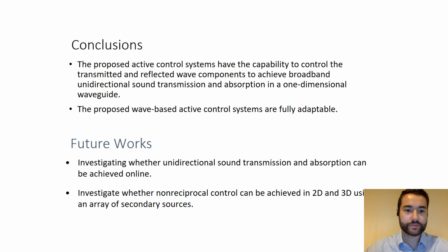So the conclusions of this presentation: we show that an active control system has the ability to control transmitted and reflected wave components separately to achieve broadband non-reciprocal sound transmission and absorption in a one-dimensional waveguide. And this control system is also fully adaptable. For future work, I'd like to investigate whether non-reciprocal sound transmission and absorption can be achieved in an online system, and investigate whether non-reciprocal control can be achieved in a 2D and 3D environment.